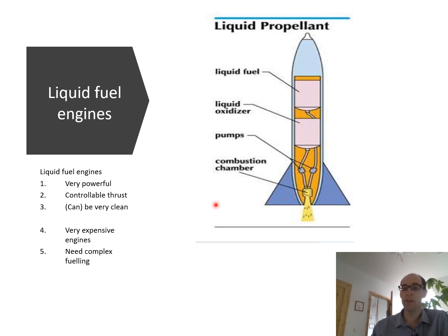For the same reason, it means that these things cannot usually be left for a long period of time fully fueled. That's not necessarily the case with all liquid fueled rocket engines, but it is generally the case with cryogenic rocket engines. And that means that you then have to defuel it if you have a launch failure, for example, or a cancelled launch sequence. And that requires additional infrastructure where you may have to pressurize the tanks, for example, to keep them inflated, because often the tanks will collapse if they are not under pressure internally because they've been built to such a lightweight design.